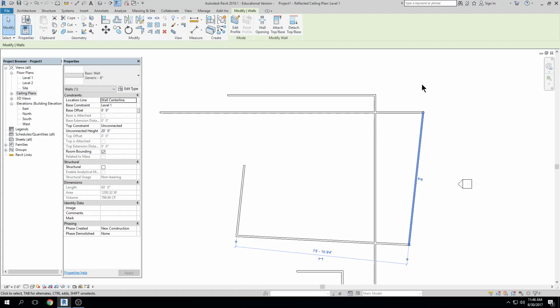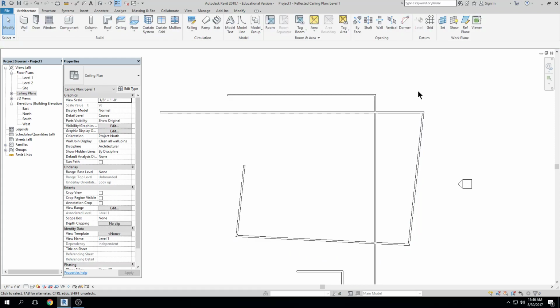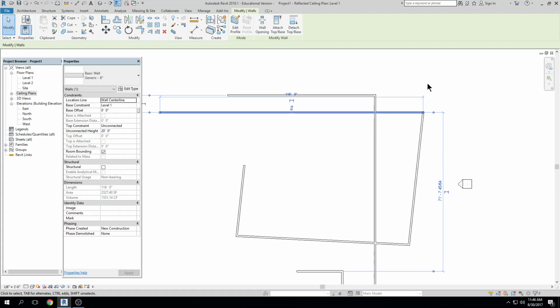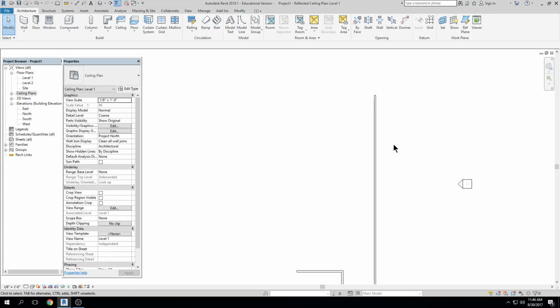You are allowed to make selections kind of precisely this way. So I'm going to hit escape, escape. I can click and pick. I can click on and hold. I'm holding the control button down. Click, click, click, click. And then I can delete, modify, rotate, copy, do whatever I want to do. If I wanted to delete these, I could hit delete on my keyboard.